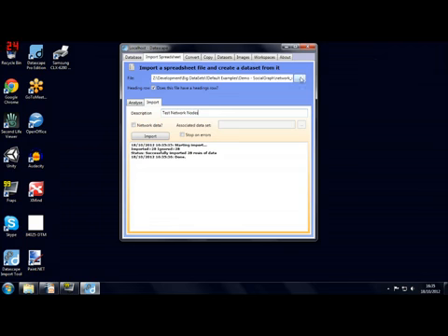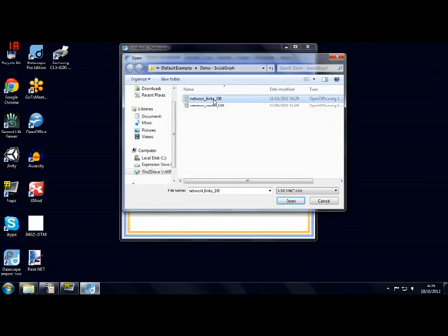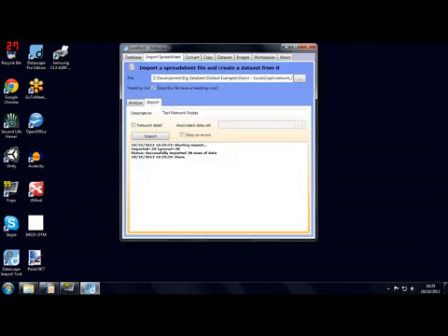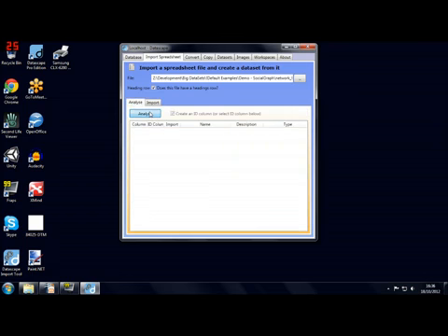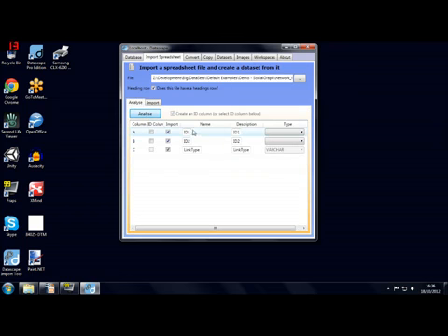So again we just browse to find our file. So this is our links file. Click on open, go back to analyze that. Here we've got our IDs and link type. In this case we do still need the Datascape to add an ID column just for reference, although we're not actually going to use it. And again just set these two to integer values.